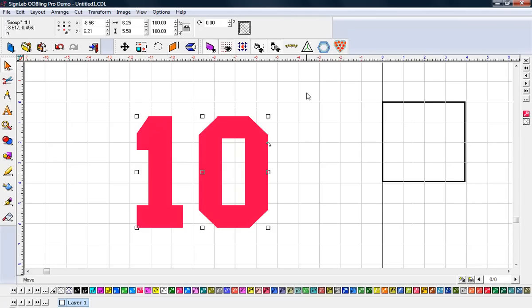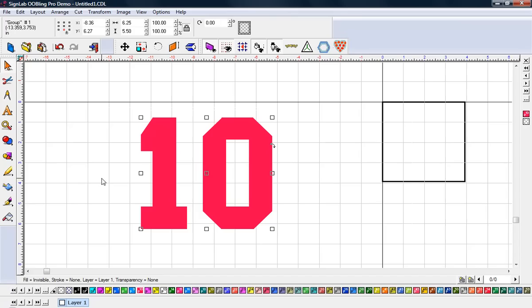The only piece that I'm missing in my cutting software that came with my vinyl cutter are the Rhinestone features. So with that said, what I wanted to show you was, first of all, in Ooing, how easy it is to create the basic Rhinestone design for the Mega Bling numbers. So if you look at this, I imported these. These are 5.5 inches tall because we're going to do an outline as well, and I want 6-inch numbers.